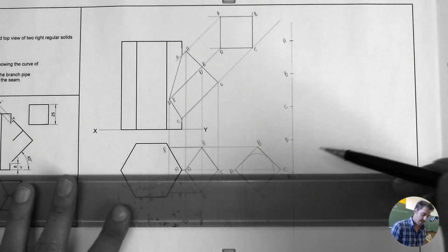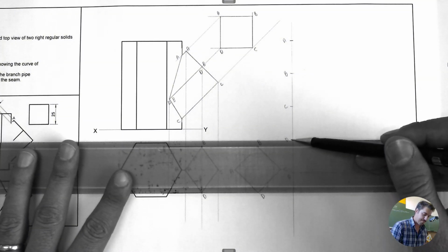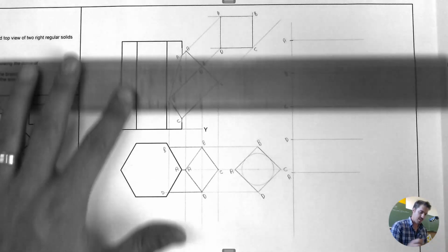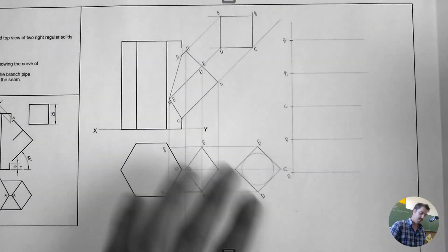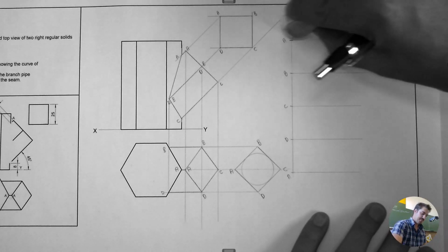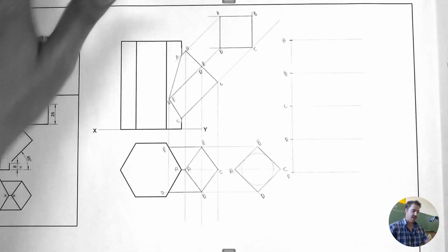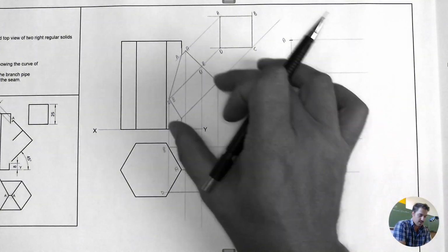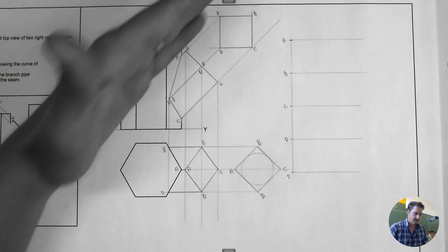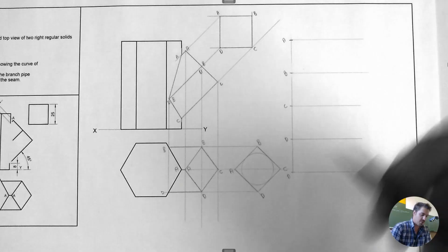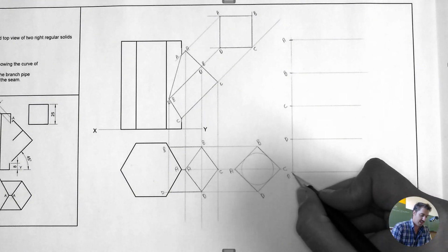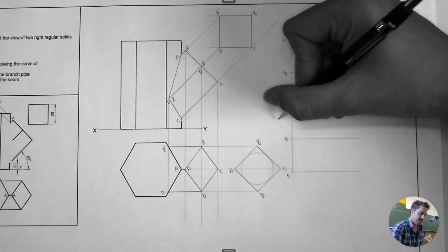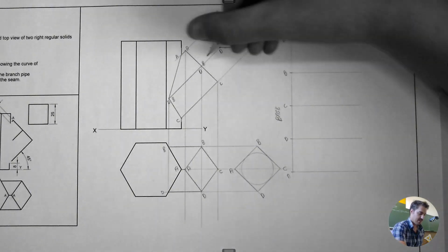Now we go ahead and we project these points up, because now we need to determine the length of the branch pipe. We've already now placed down the base. Remember, this base can be placed anywhere. Some people like to just take these points and project it on the angle that the branch pipe is intersecting into the main pipe here. But using it this way, it means you can just project it anywhere you would like. So now we actually start going from the base. This is considered to be the base.